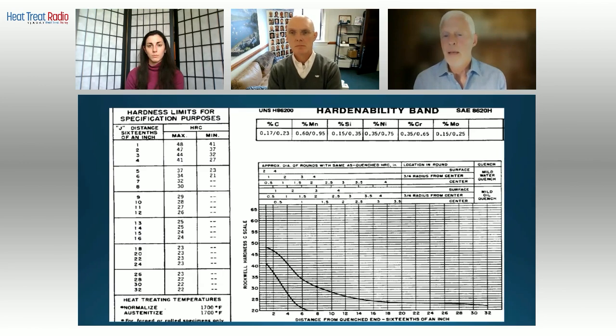So we do know that if you had a fast, petroleum-based oil, it was very fast. You may experientially, if you had a heat and you knew that it had a J3 of 40 and you're consistently seeing 44 out of it, then what you would have to say is that in your specific instance, your quenchant is more aggressive than what this chart was built to simulate. However, you can continue to use the chart. It's just that you have to use your experience in doing it.